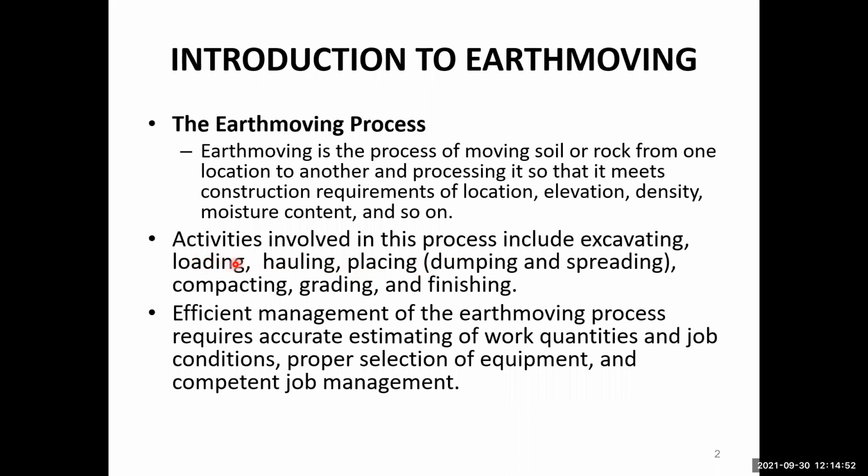So the activities involved in this process include excavating, loading, hauling, placing, that means dumping and spreading, compacting, grading, and finishing. Excavating means you are digging the soil, you are removing the soil, and then you are loading it into the dump trucks. Hauling means you are transporting it from one location to another, and then you are placing it, that means dumping it and spreading it on the desired location. And then after that, there will be compaction, and then grading, and then finishing.